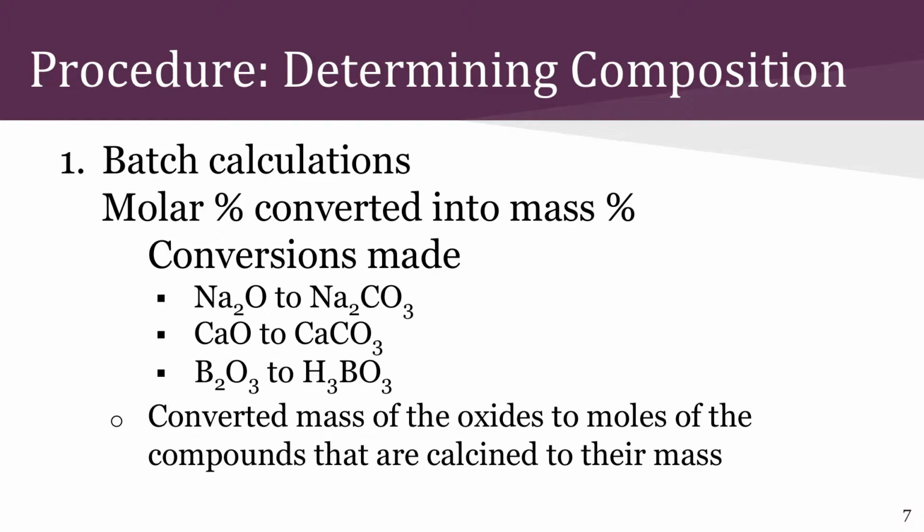As stated previously, we wanted to reduce the total cost of producing our glass. Therefore, we reduced the amount of silicon dioxide, which has a high melting point. By doing this, we reduced the melting point of the glass and therefore utilized less energy to produce the glass. At first, we were presented with molar percentages, which we then converted into mass percentages. And with these mass percentages, we were able to determine the relative amounts of each ingredient in grams.